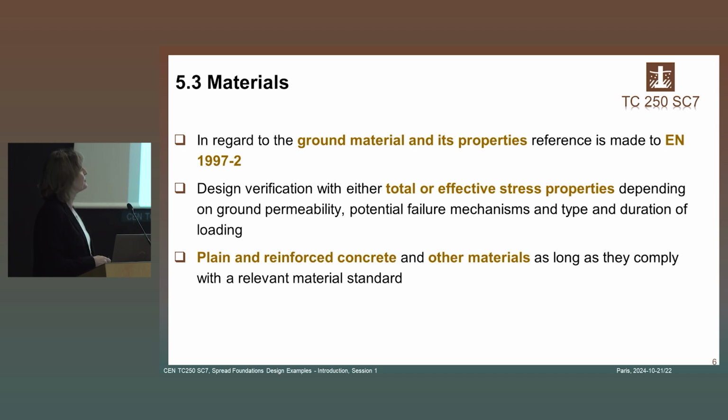And for that you need to choose the appropriate total or effective stress properties. The type of material of the footing itself is also mentioned, let's say plain or reinforced concrete, and it is stated that these materials should comply with relevant material standards.